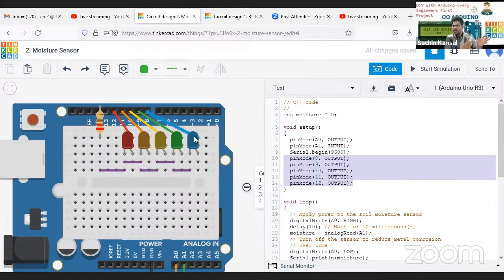So all the LEDs are connected in series here. You can see now this is being connected, but where is the ground given? You can give the ground based on a single resistor, right? So you are just connecting one single resistor, and based on this, you are doing what we call shorting. So you short the wire. You can see this is shorted here. This is again shorted. This is again shorted in this line. So ideally, you can connect it in series and you short this wire, so everyone will get the negative ground. You don't need to connect it individually. You have shorted this complete grid.